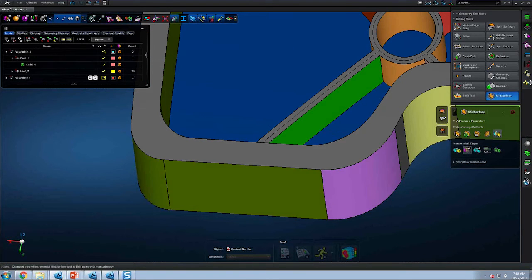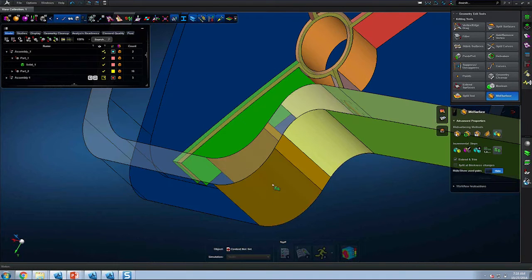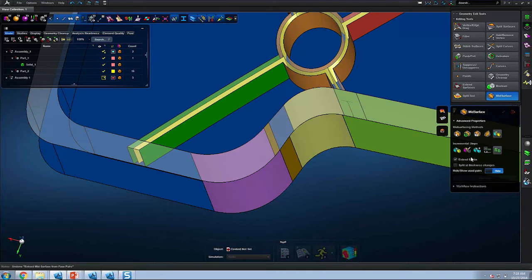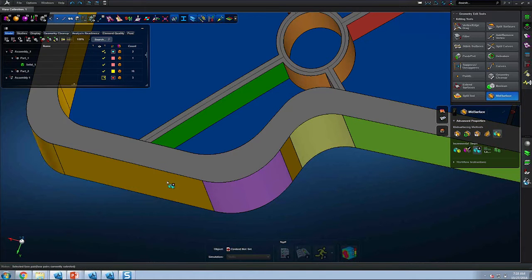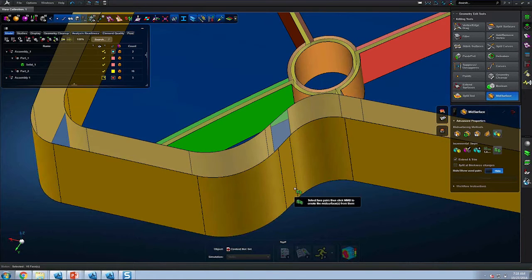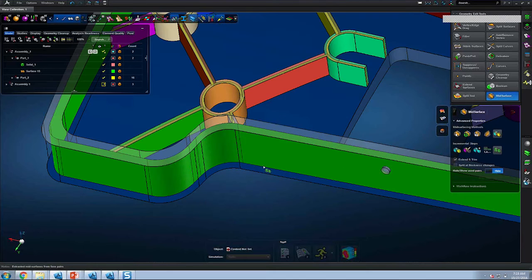Now again, I can do the same for this. I can create a pair here. And when I actually do go ahead and create a midsurface piece, I have confidence that there will be a continuous midsurface here. But again, we still have the issue where we have to merge these midsurface pairs together. And here, let me merge all of these together. And you know you're merging when they turn golden like this. And then after you confirm the edit, they all become one color, indicating they are one continuous pair. And now when I go ahead and extract the midsurface, we now have a running continuous midsurface throughout this rib.